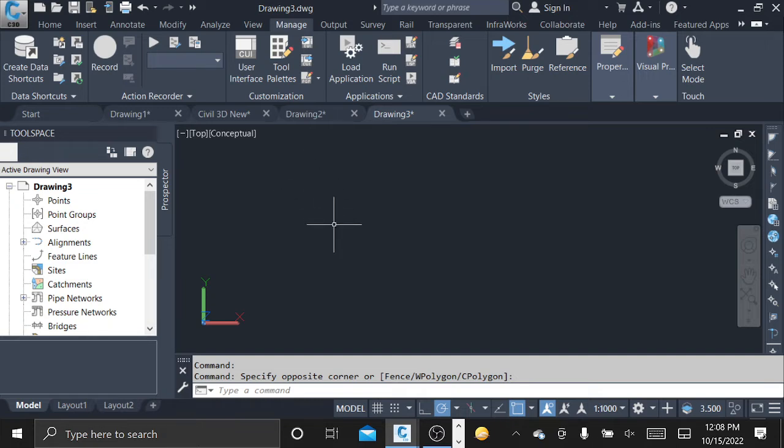Sometimes you can create a data shortcut that some people can use, where you have, say, points imported in, and you've created, say, a surface, but you want to have different perspectives from different engineers. Now, once you create data shortcuts, people will always be referring to that data. Once the default information of that data changes, it will also equally update for the other individuals.